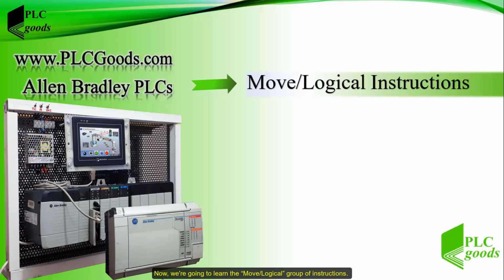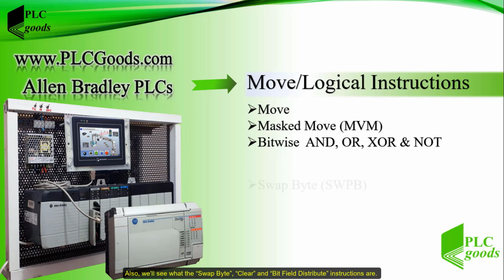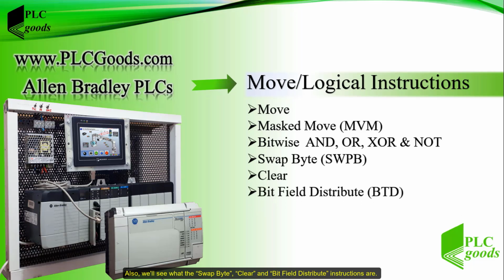Now we are going to learn the move logical group of instructions. We will start with the move and mask move instructions. Then we will learn logical bitwise instructions. Also, we will see what the swap, byte, clear, and bit filled distribute instructions are. Finally, we will do a simple project using these instructions to turn on 8 fans of 8 industrial cabinets.